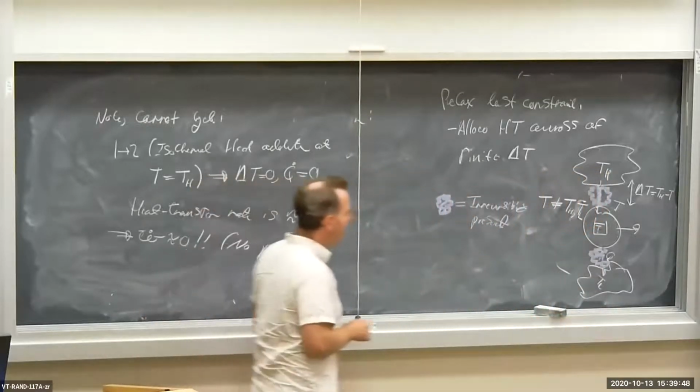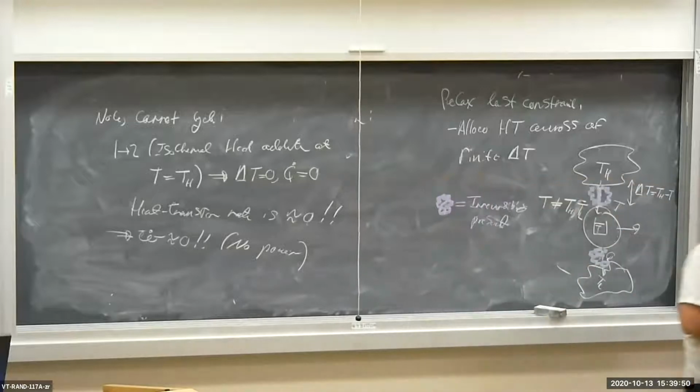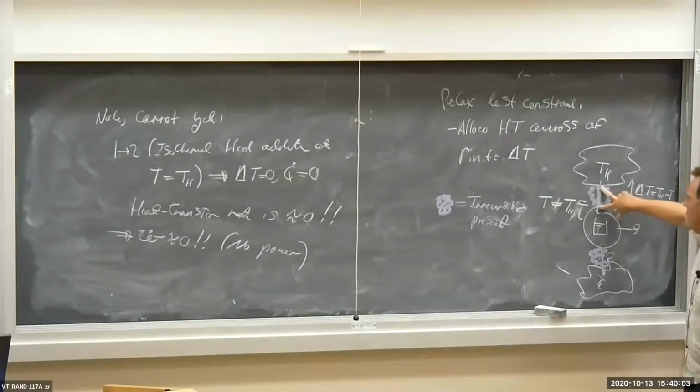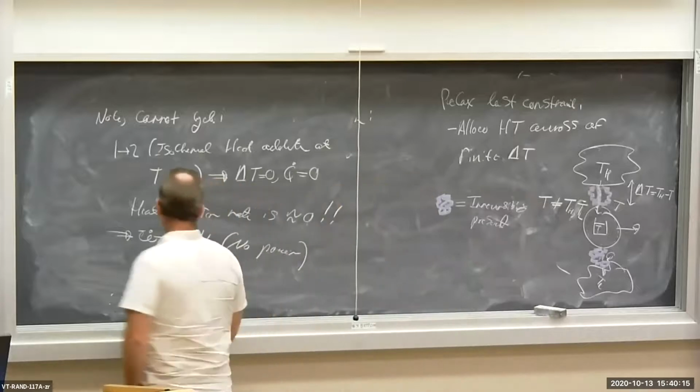So we're going to allow for external irreversibility in our cycle, but not internal irreversibility within our cycle. We do that so we can actually get some heat transfer. We want a delta T here, a finite delta T. In fact, the greater the delta T, the more the heat gets transferred per unit time and the more power we produce. Okay?